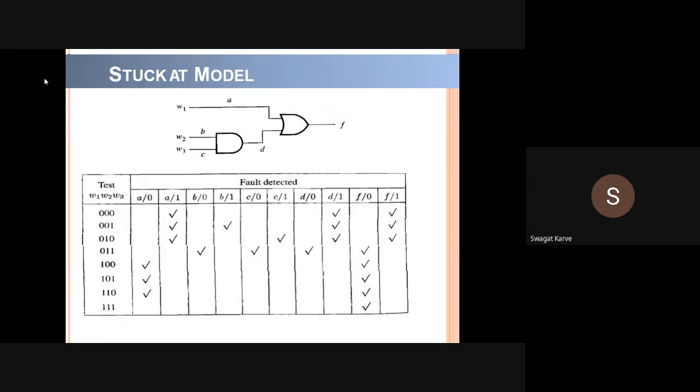Again come to the second pin. For that second pin you have to follow the same strategy. First, consider it is permanently damaged and connected to a logic 1, then connected to a logic 0, check the output. Similarly, you have to carry out such two cases, right? To a logic 0 or to logic 1.